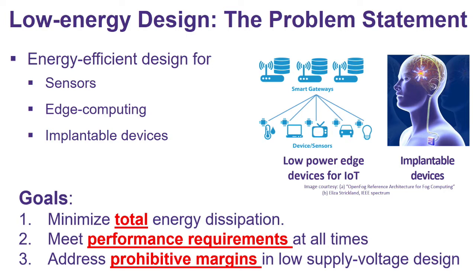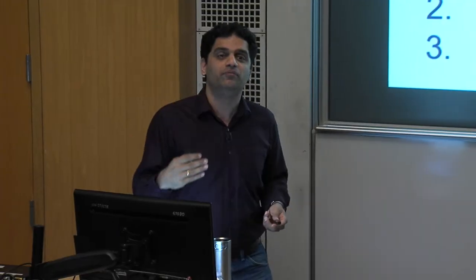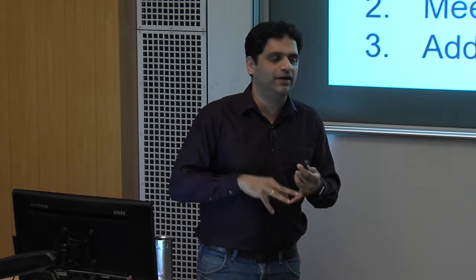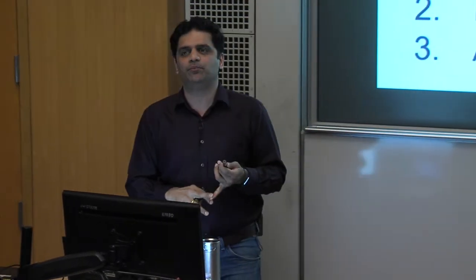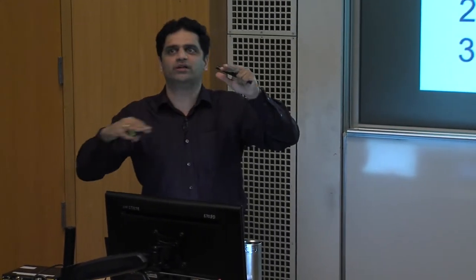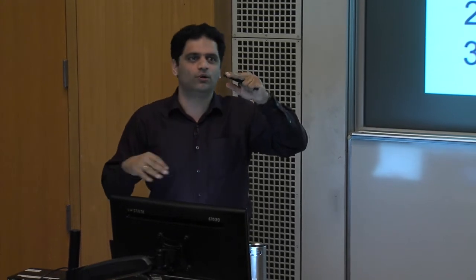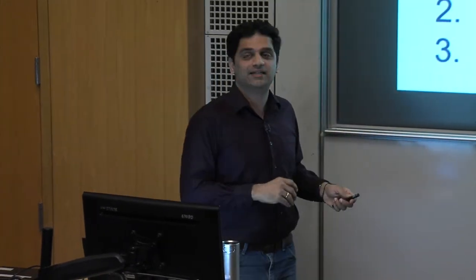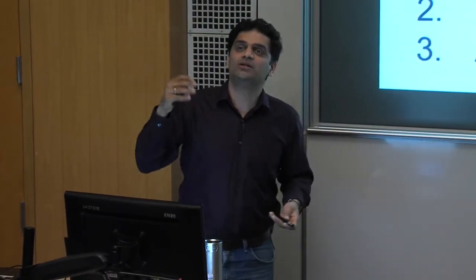Third, when you do low voltage design, you actually have to provide a lot of margins. Low voltage circuits are very sensitive to environmental factors like temperature, supply noise, and you have to aggressively margin for them with an extra voltage so that the circuits are safe and they don't slow down and fail timing, things like that. And these margins are prohibitive. By the time you account for all those margins, the whole value proposition for low voltage design begins to erode, right?